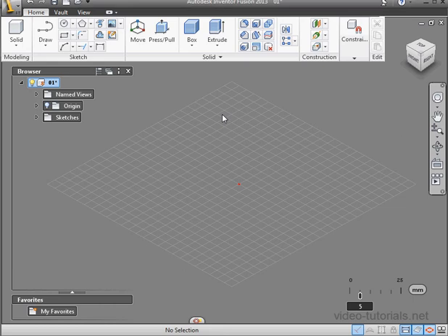In this tutorial, I'm going to teach you how to use geometric constraints in Inventor Fusion. Let's toggle off Precise Input and Snap modes and activate the Rectangle tool. We'll drop a rectangle about here.